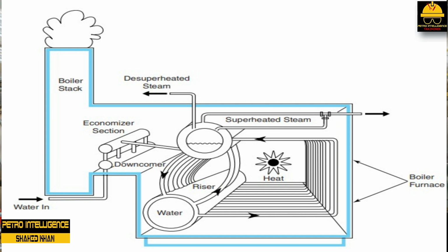Circulation continues, and makeup water is added to the upper drum to replace the steam that is generated. Water circulation continues in a water tube boiler because steam bubbles in the lower drum move up the riser tubes and cause water density to decrease. The cooler water in the downcomer flows into the mud drum. The riser and steam generating tubes are physically located near the burners.